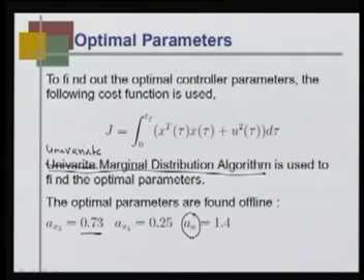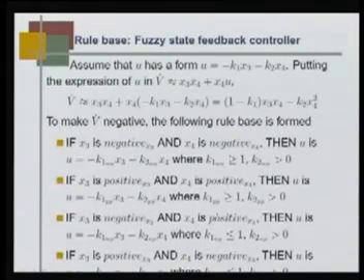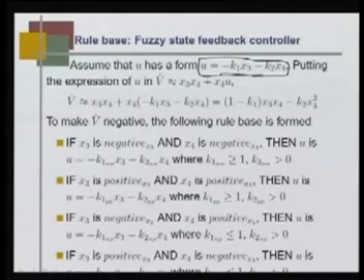Now, we can simulate the system, which will show the results at the end of the section, but here before that I will derive another kind of rule base for the same system. So, the U, instead of earlier case where U was simply a linguistic variable, now I am assuming this is a state variable feedback technique, where U is minus k1 x3 minus k2 x4.